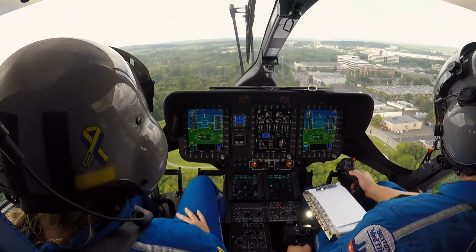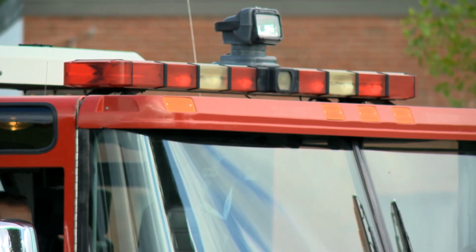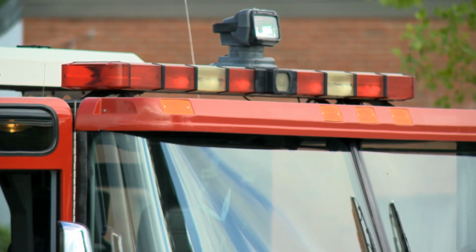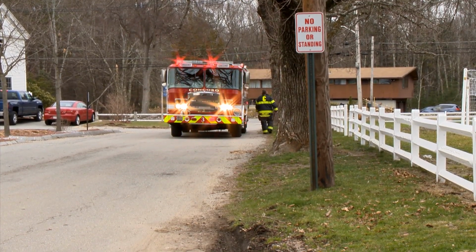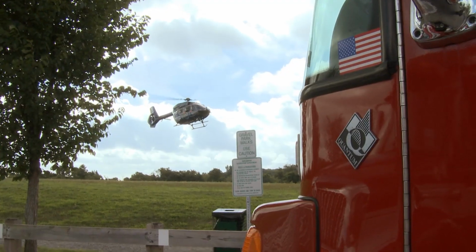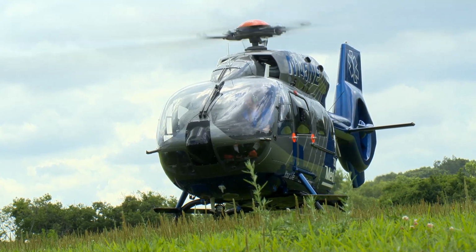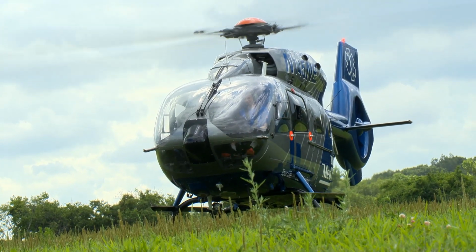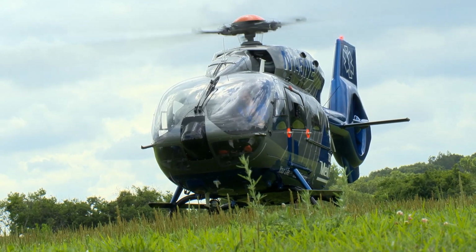The pilot may ask LZ command directly or through our communication center to keep headlights and other high visibility flashing lights on if certain lighting conditions and other circumstances exist. All vehicles must remain outside the 100-foot by 100-foot landing area. An aircraft should always be considered dangerous, whether the rotors are rotating or appear to be stopped.